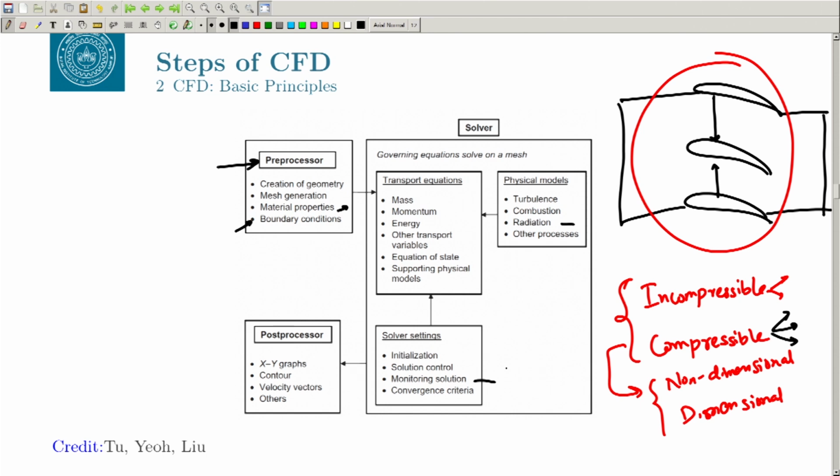In the RANS simulation, you can say that okay, when it reaches 10 power minus 5. When I say it reaches 10 power minus 5, what do I mean? It means that I am looking for a steady state solution, a solution where density has got a certain value at a given point.